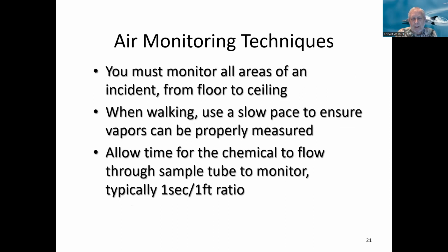You must monitor all areas of an incident from floor to ceiling. When walking, use a slow pace to ensure the vapors can be properly measured. Allow time for the chemical to flow through the sample tube to monitor, typically 1 second per 1 foot. So every foot will move at about a second. So it has to be slow enough for the meter to read it. If you go too fast, you might get ahead of yourself and you'll be into a reading that's too high when you don't want to be.